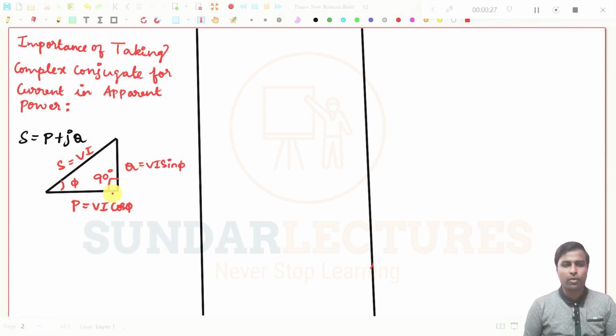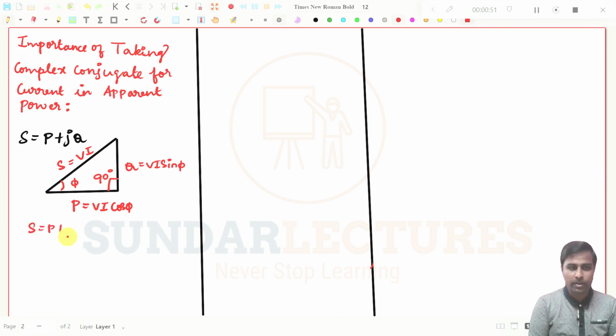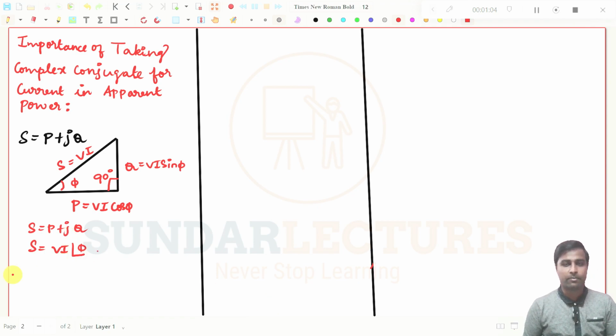So, we know this triangle, right? This is the power triangle. This is real power, this is reactive power, and this is the apparent power. S is equal to VI, which is the apparent power. VI cos phi will be real power, and VI sin phi will be reactive power. We know this one already, right? Or we can write it as S is equal to P plus jQ, or S is equal to VI at an angle of phi. We can write like this.